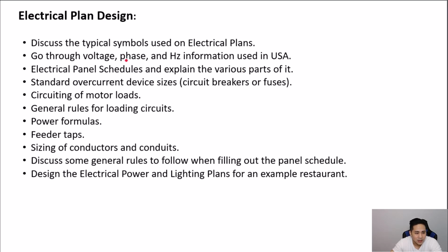And the voltage typically is like about 120 or 208. The phase just represents how many of those hot, energized phases are going to a particular panel or a circuit. And the hertz is the frequency of that alternating current voltage.